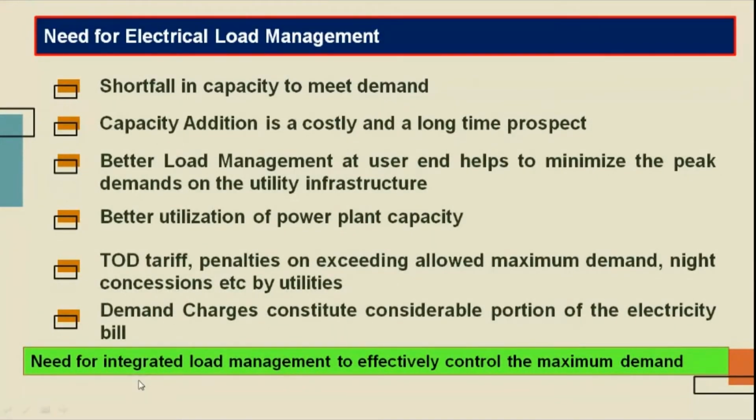So that's why there is a need for integrated load management to effectively control the maximum demand. Then only we will be able to make use of our power plant in the best possible way, and the consumer will be able to pay the optimum amount in case of the tariff. So this is all about the need for electrical load management.